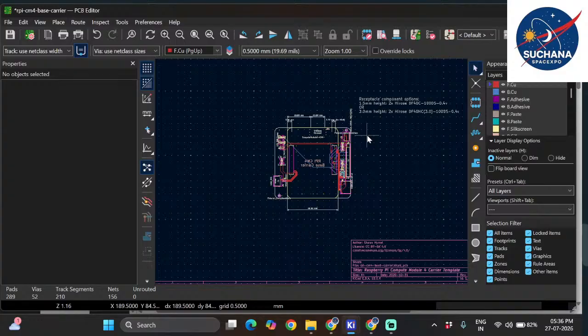As of now, what you need to understand is that the NCP 1117 IC is a low dropout voltage regulator, which is used in a few variants of Raspberry modules and also in Arduino Uno. Coming to the difference between them, in the Raspberry modules it has a fixed output voltage of 3.3 volt, and the same NCP 1117 IC in Arduino Uno produces a fixed output voltage of 5 volt. Coming to another thing, I also mentioned the MXL 7704. I'll show you that.